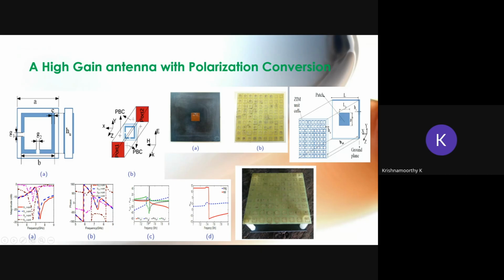This element is going to give that lens kind of operation, because this is going to give that near zero refractive index. The refractive index of this kind of material we have calculated, it's shown here. The refractive index is going to be near zero. Both epsilon and mu values are going to be near zero, less than 1.